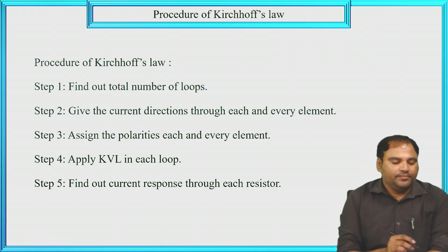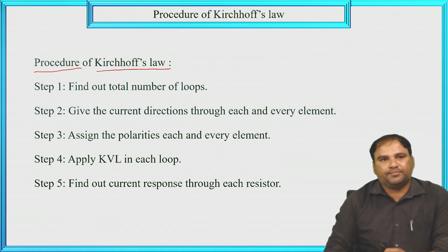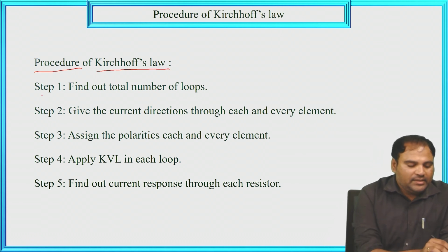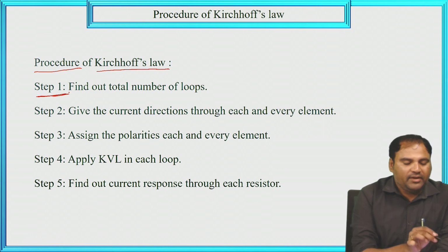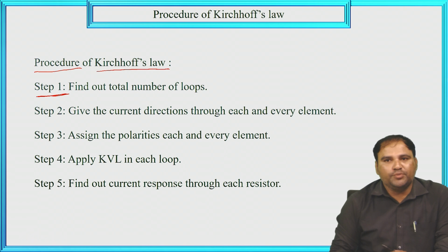So here we are having the procedure of Kirchhoff laws. In that, what is step number 1? Step number 1 is, first of all, we need to find out the total number of loops in a given circuit.